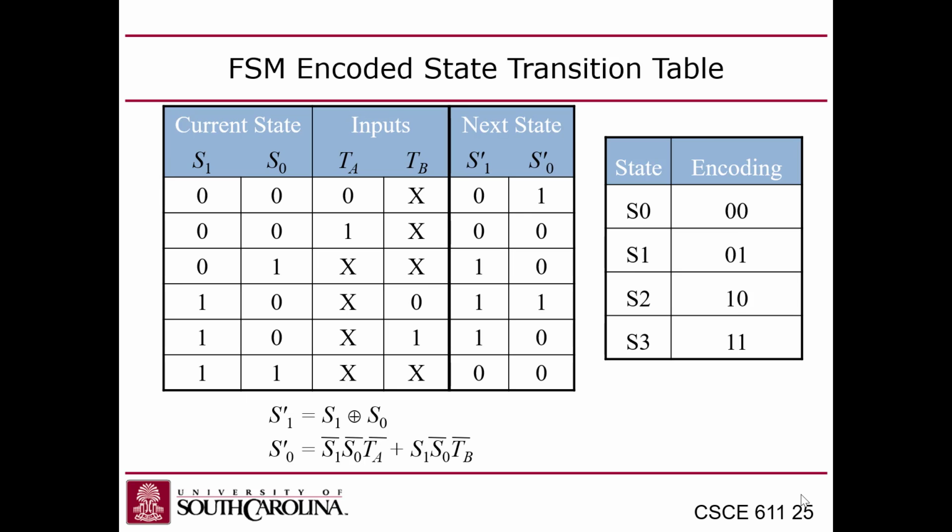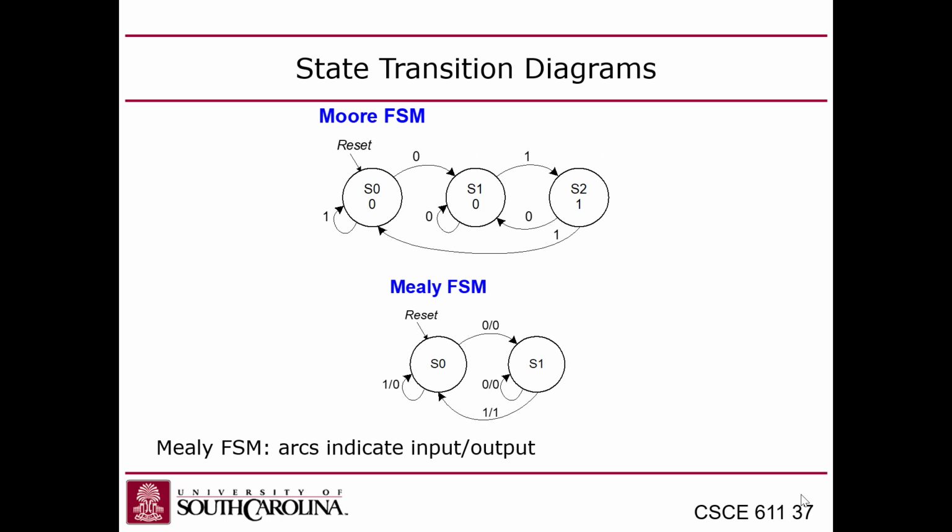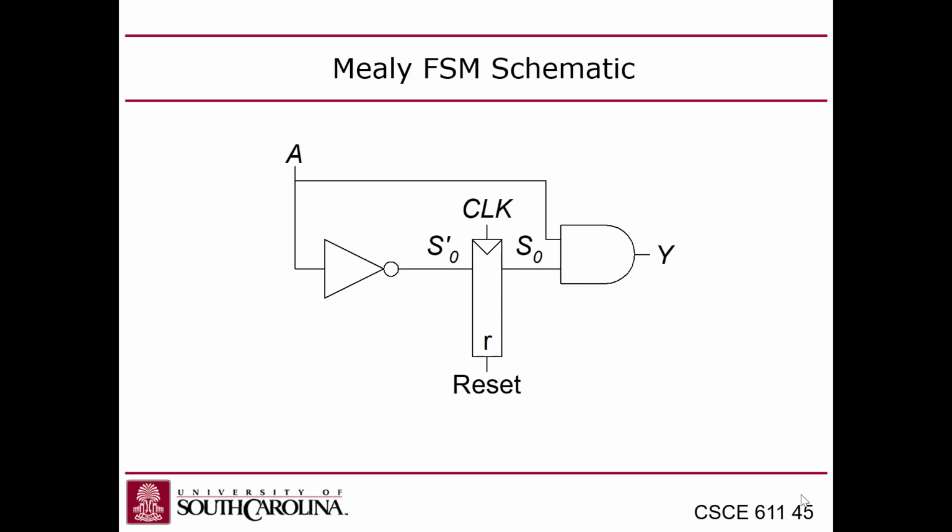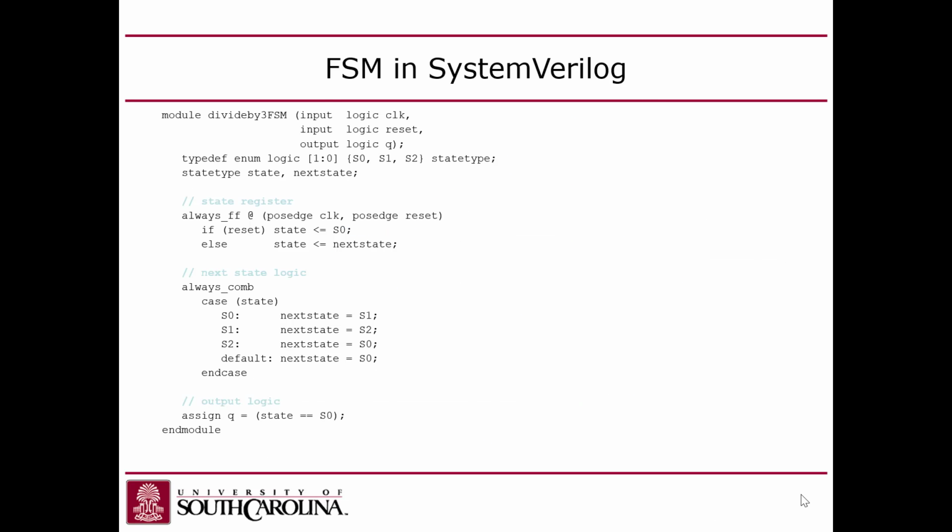In System Verilog, they made it a little easier, where they allow you to create an enumerated type, in this case called state type, although you can call it whatever you want. And you could just list the states in there. You could actually name them in there. Now, to be honest, I always have to look this syntax up. I never remember the syntax for this. But they have typedef, enum, logic, and then you still have to give it the number of bits.